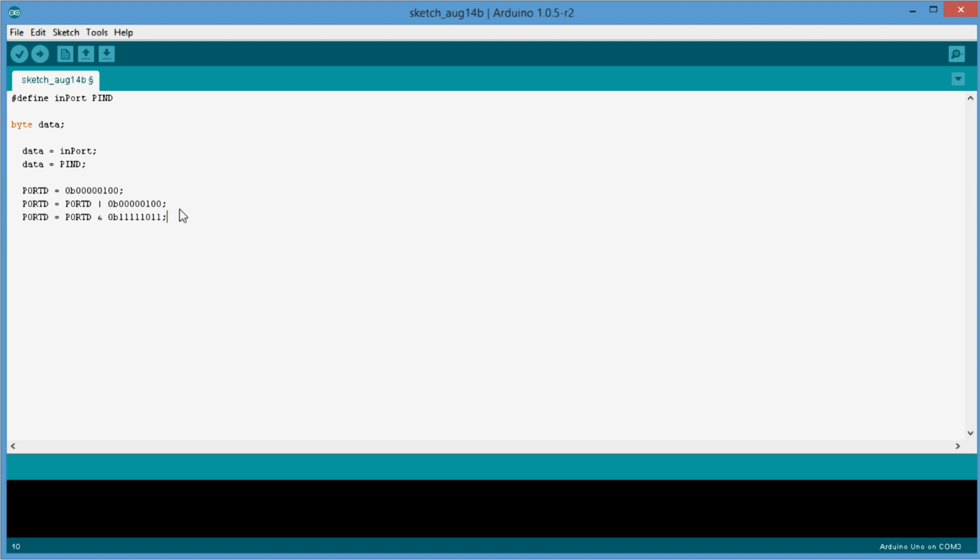Now in the native code that the microcontroller understands, there are instructions that will set or clear a single bit on a port, and that's one instruction. So the compiler generally is smart enough to know that there's only one bit being changed here, so it's going to change this whole C statement into one single assembly instruction that the microcontroller can understand. If I needed to affect more than one bit here, but not all of them, I could just write those myself like that, and that would do the same thing.